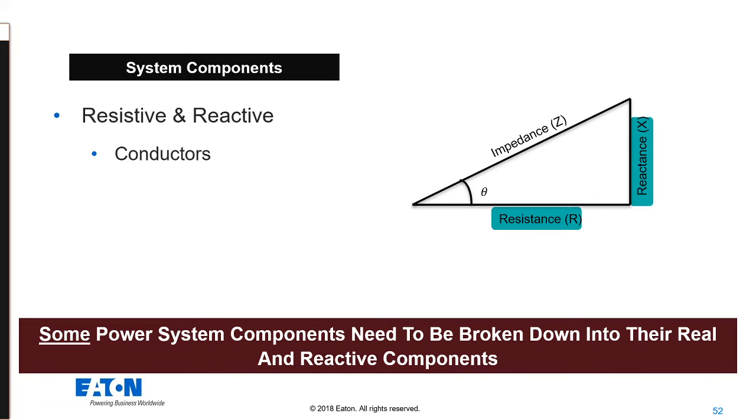And then you have your conductors. Your conductors are typically resistance and reactance, and you'll have an effective impedance Z with regard to conductors. I'll show you that Table 9 in the National Electrical Code reflects that, and we'll use this information for voltage drop.